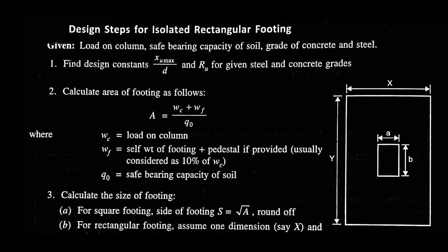Before going to step 2, I would like to share with you the concept of Ru. Ru depends on Xu max by d, which is dependent upon grade of steel and grade of concrete.